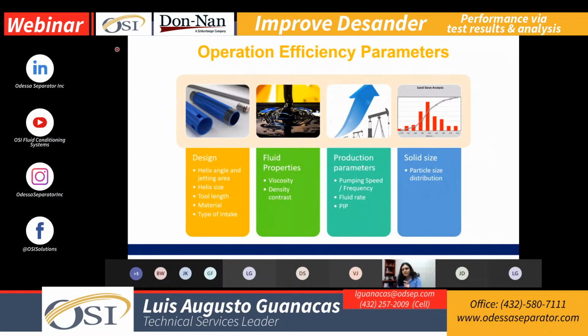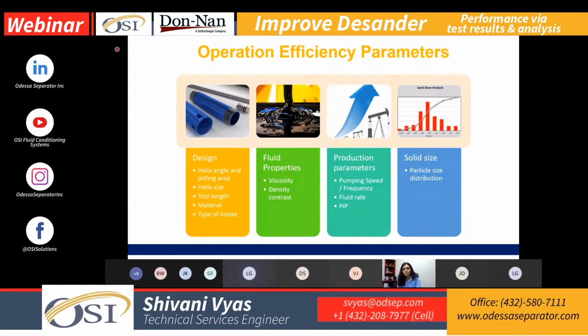If the particles are much coarser, like you were talking about, we would have to adjust it and design it accordingly. Versus if the particle size is really fine, like 100 mesh, we'd have to adjust that centrifugal force creator accordingly. That way, that separation is created, and that's what is critical at this point.